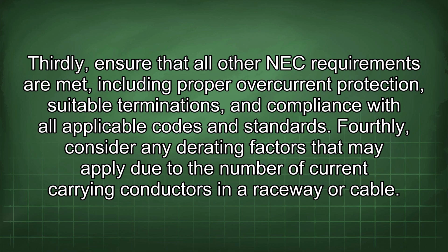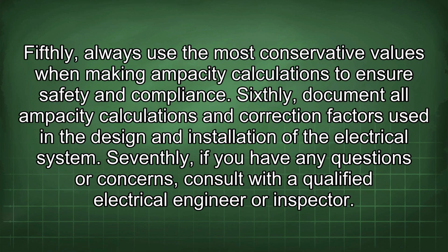Fourthly, consider any derating factors that may apply due to the number of current carrying conductors in a raceway or cable. Fifthly, always use the most conservative values when making ampacity calculations to ensure safety and compliance. Sixthly, document all ampacity calculations and correction factors used in the design and installation of the electrical system. Seventhly, if you have any questions or concerns, consult with a qualified electrical engineer or inspector.